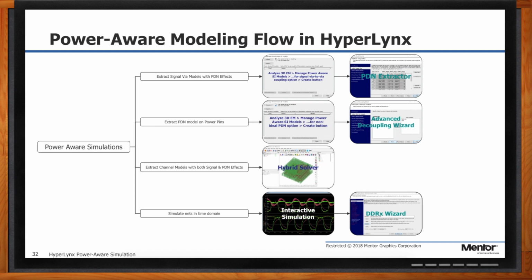The reality is there are lots of good reasons to use different settings on that knob. Most of the time, when I crank the detail knob all the way to the right, my electromagnetic solution time goes way up, my simulation time goes up, my throughput goes way down, my ability to meet schedule goes down. And the fact is, a lot of times you don't need it.